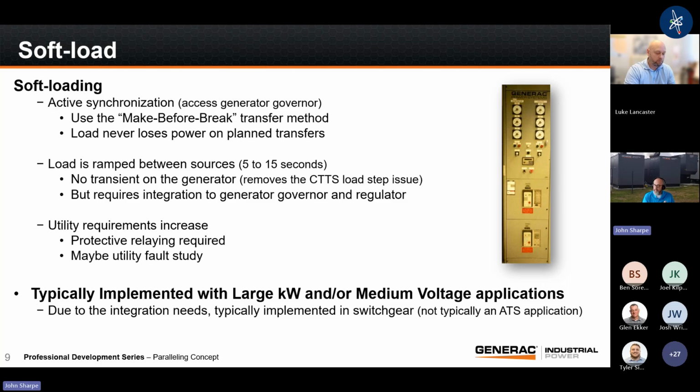Schweitzer SEL's 751 relay is what I see the most. Not a commercial for Schweitzer, but that's the relay that I see the most, something to be able to protect the utility. You need to meet the interconnect requirements of the National Electric Code, NEC 705, and that is typically going to point you to the standard for interconnection to utility, which is IEEE 1547. SEL used to have a 1547 relay. Today, they just use the 751 feeder protection relay. It has the same functionality.